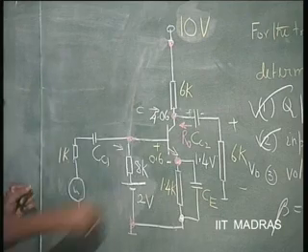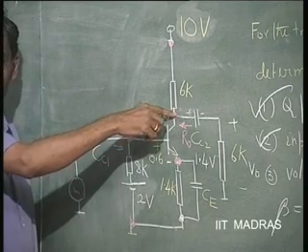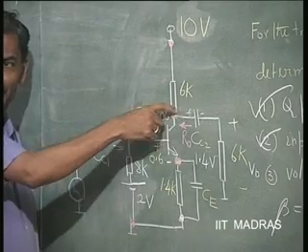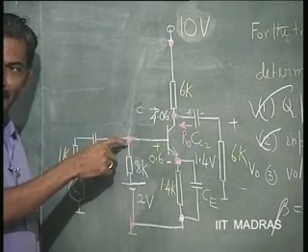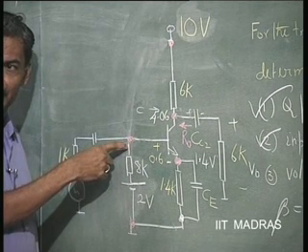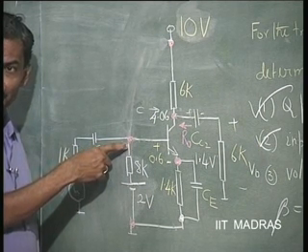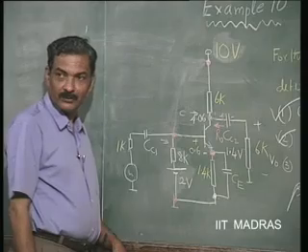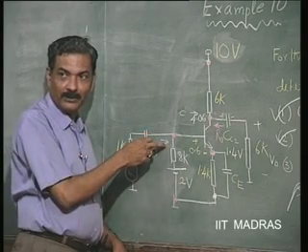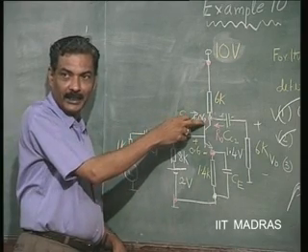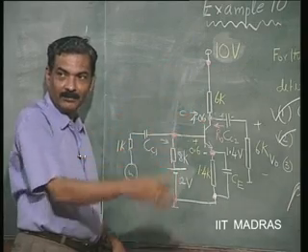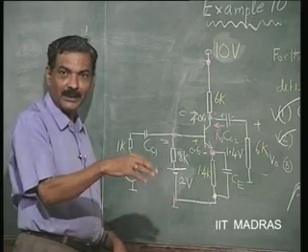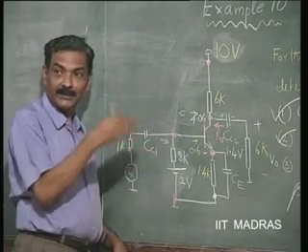But this voltage is going to keep increasing and decreasing. When this is increasing, this will decrease. When this is decreasing, this will increase because of the phase shift. But now, for a large signal, I can still assume that this voltage remains essentially constant at 2 volts. Now, this voltage is changing from 4.06 volts. Suppose I apply 10 volts, this will be swinging from 4.06, all the way down to 4.06 minus 1.14 and 4.06 plus 1.14 if it is assumed to be linear.